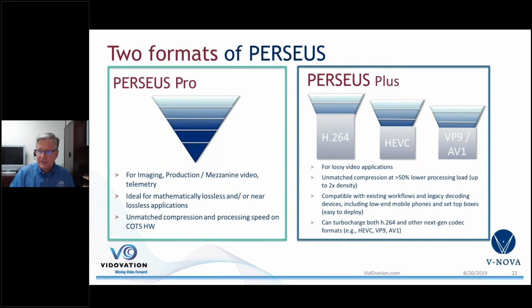So an H.264, an HEVC, VP9, AV1, and it sits as a secondary channel, and it looks for the error. It compares the H.264 compression to the original content, and in a loop comes up with that different signal, that error signal. So it analyzes and it adds extra clarity, extra resolution to industry standard codecs out there.